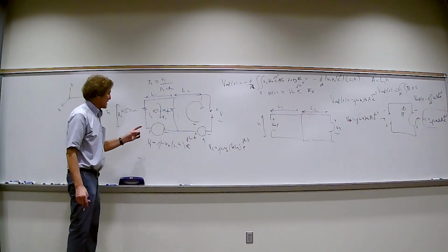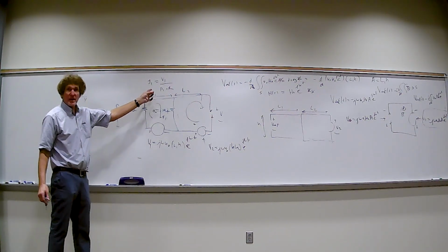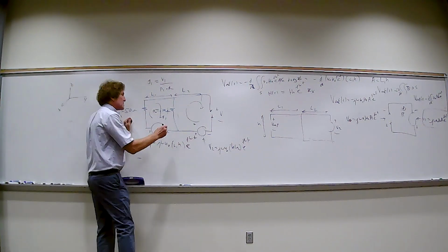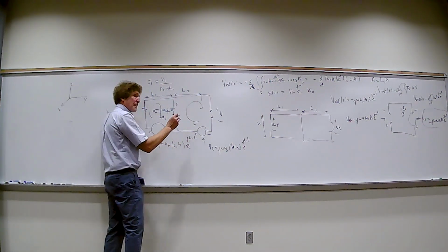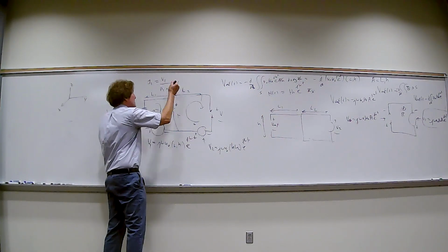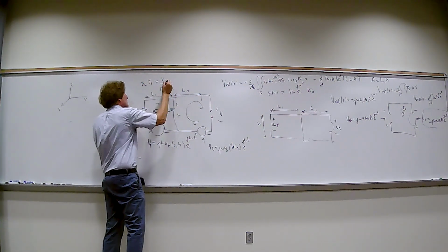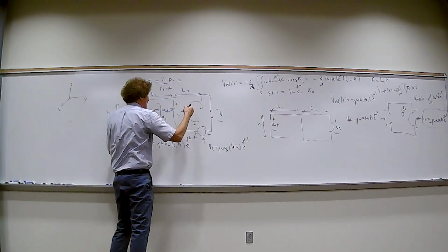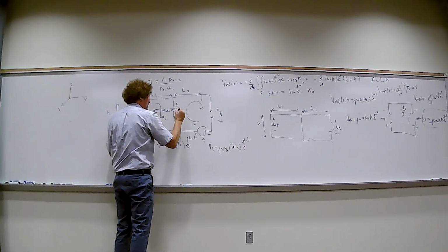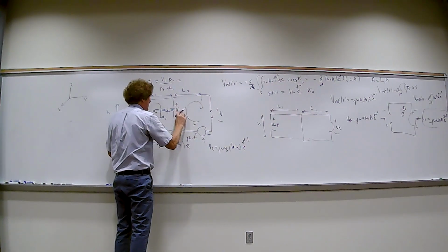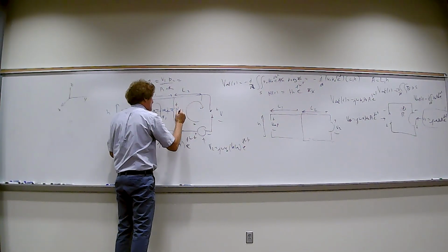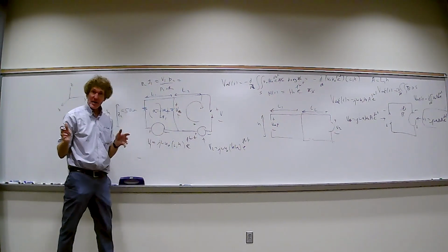How would you do it? Well, you've got the current here, right? Now, if I want the voltage on this one, what do you do? You just take this current times resistance, which I called R2. And now you have the voltage across here, call it V2, or VR2, right? Y'all hear me on this one?